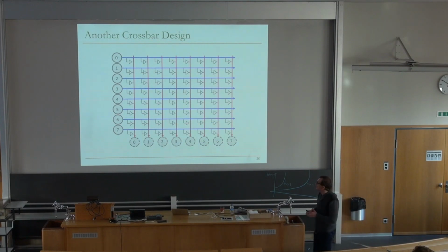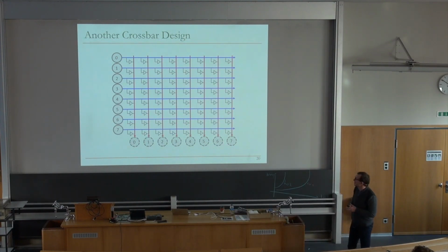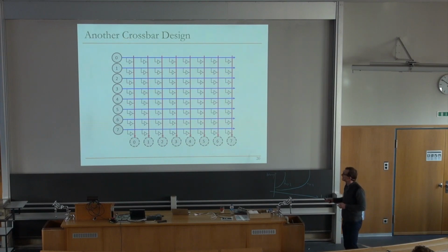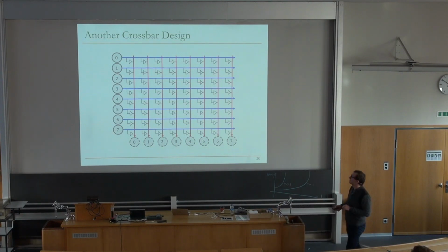And now you run into other trade-offs, right? If, for example, you have buffers, maybe you put the arbitration complexity over here. If you don't have buffers, then you need to somehow sense if somebody else is going to send something to this link. So there are different ways of building this arbiter. There are bufferless arbiters, there are buffered arbiters. We're going to look at that later on again, but keep this in mind for now. How you do this arbitration is not so easy.